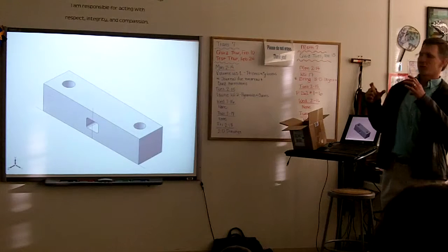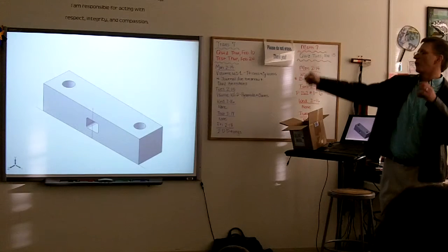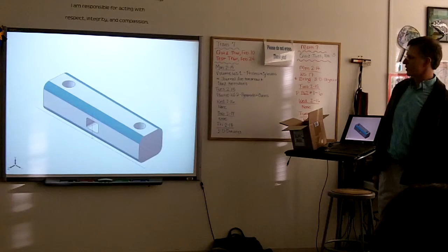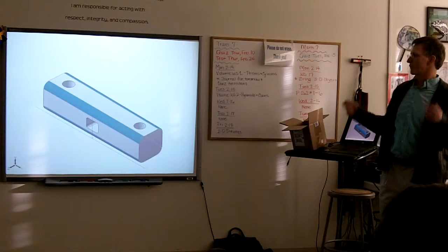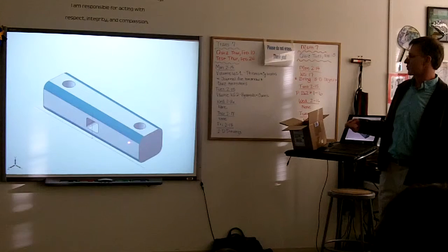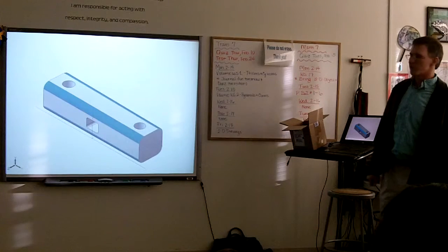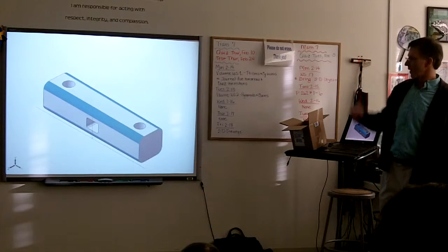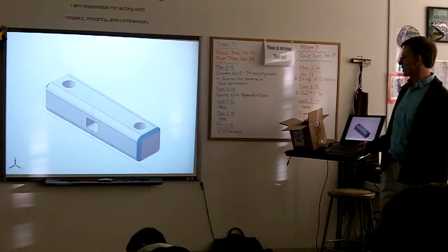On that sketch, you create a rectangle, and you tell it to now extrude that hole. So now we have a part with three different holes, and so on and so forth. The software has other features that you can perform common operations on an individual part. This is called a chamfer, so it just rounds off the corners that you select. So you would select a line, you hit chamfer, and it'll round that over to a radius that you specify.